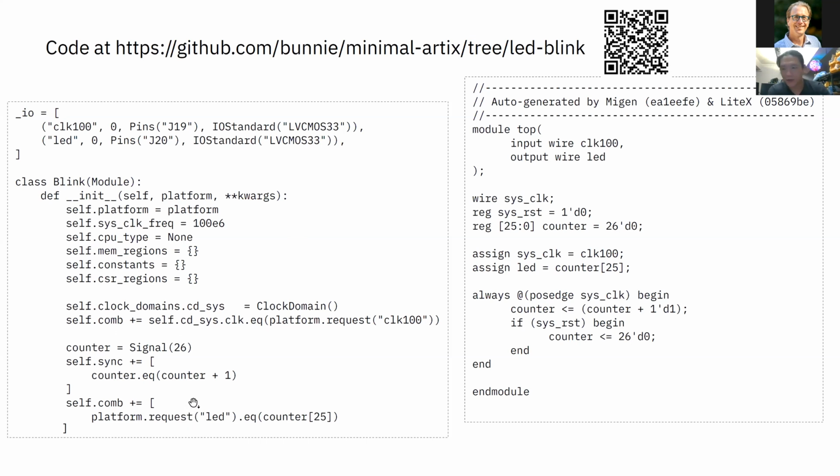You go ahead and pull this into Migen, and it creates this Verilog on the right-hand side. That's the exact Verilog that's inferred from this. You can see, okay, here we go. I have the arrows. You can see that the self.sync here ended up inside a posedge sys clock, exactly as you'd expect. Counter is counter plus 1. It automatically decorates the resets for you. You didn't have to talk about that. That was implicit with the language.